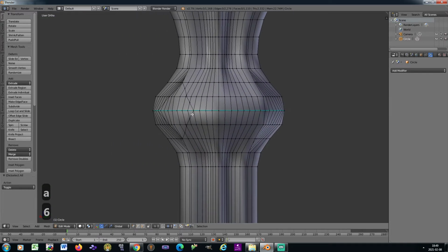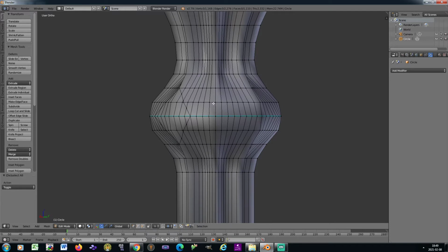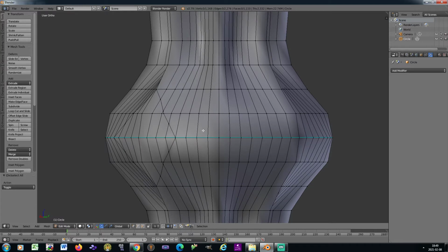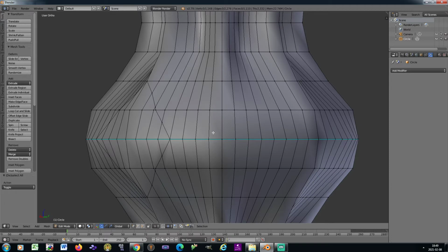It's a good idea to go into the preferences and set the rotation of the scene to 45 degrees per pressing of the 6 key on the numpad, so that your model rotates 45 degrees at a time. If you haven't done that, I recommend doing this, at least for this model.